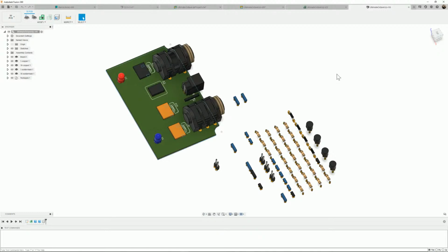If you tell it the stencil thickness, and it knows the stencil aperture, and you have a library of different solder paste materials, you can tell it what paste you're using. It will output and render the fillet you'll get, and give you a warning if there's too much solder that it's going to ball up and run all over your board. I think that would be super cool.